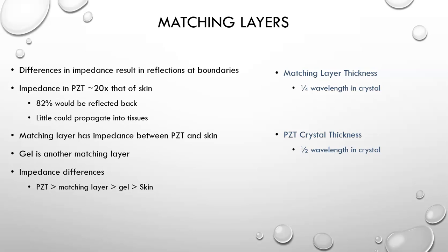And so you see these layers of matching impedance differences, the piezoelectric, the matching layer, the gel, and the skin in that order. So the impedance then allows more of the sound to transfer into the body and back from the body back to the transducer.